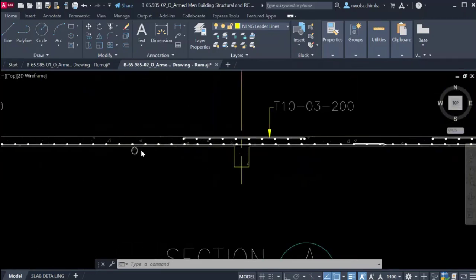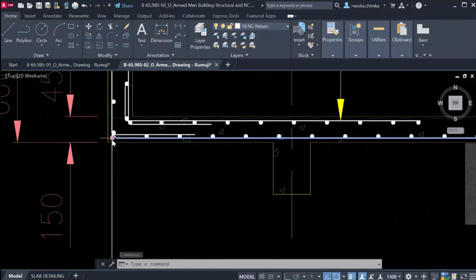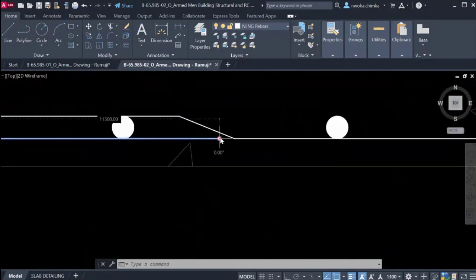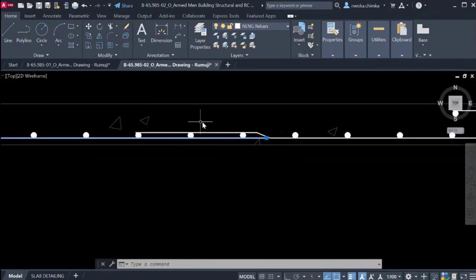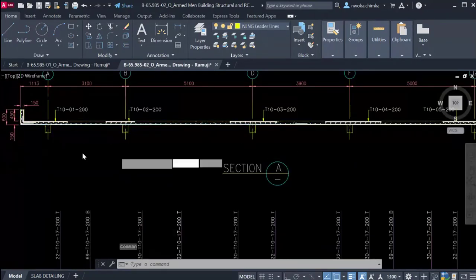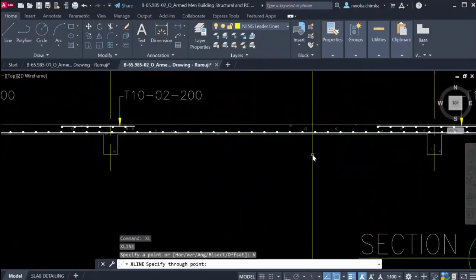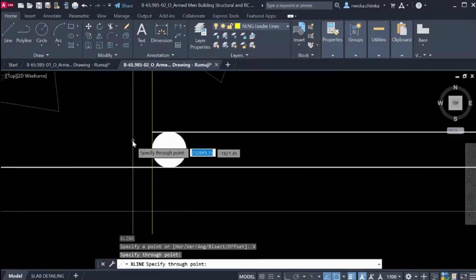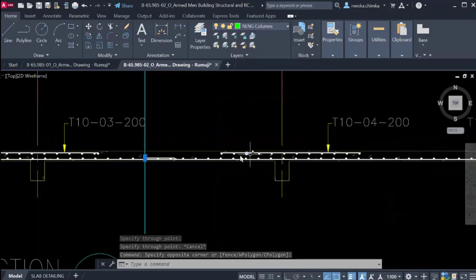So this reinforcement of this bottom bar runs all the way from this place, 11.5 meters, down all the way down here. Reaching here, the whole length of reinforcement was exceeded. So we now have to bring out this reinforcement and lap it all the way down here. We will now have to delete this and establish another one again, which is vertical from this point, which is the point of our lapping. So from this point again, we establish this and change the color so that we will not be confused, because we already have yellow as our grid line.